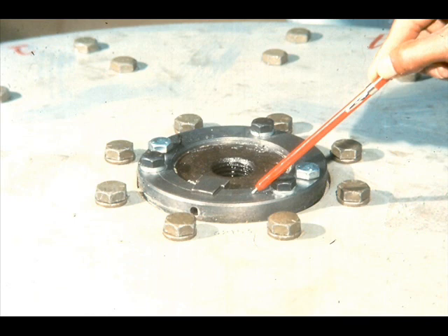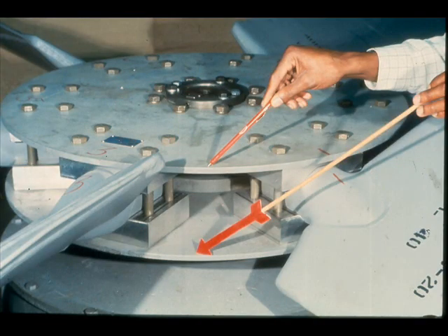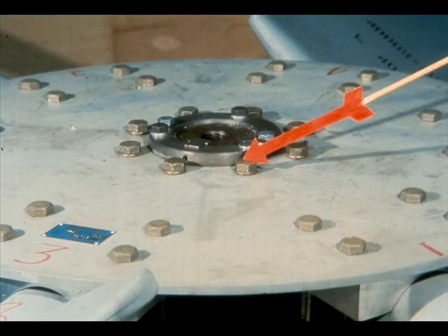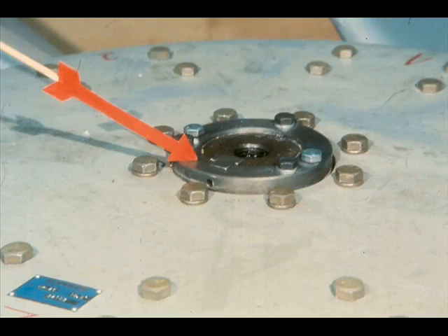The center of the fan is called, quite appropriately, the fan hub. The hub is actually a short, solid sleeve, with two hub plates mounted on it, one on the top, the other on the bottom. The two hub plates are secured to the hub with these cap screws, now being pointed out. The hub itself is secured to the drive shaft through this split tapered bushing. The bushing is tightened down with the cap screws on top, clamping the bushing around the drive shaft and forcing it into the tapered hub. You'll understand it better when we take it apart during the next segment.